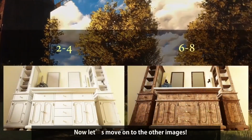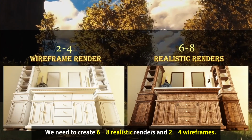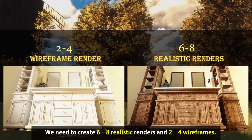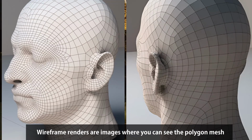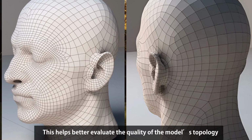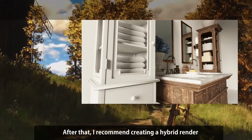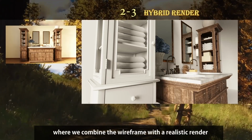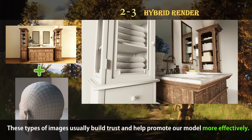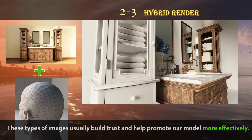Now let's move on to the other images. We need to create 6 to 8 realistic renders and 2 to 4 wireframes. Wireframe renders are images where you can see the polygonal mesh. This helps better evaluate the quality of the model's topology and how it's been built. After that, I recommend creating a hybrid render, where we combine the wireframe with a realistic render. These types of images usually build trust and help promote our model more effectively.